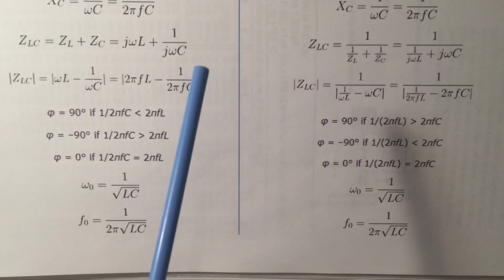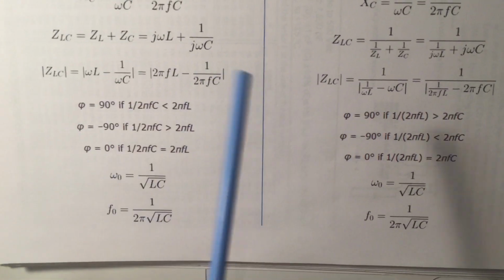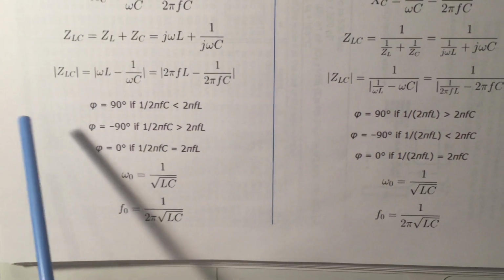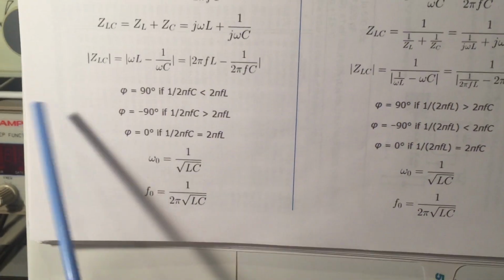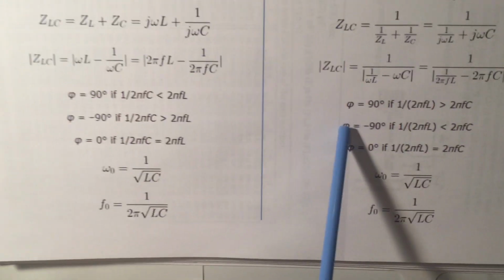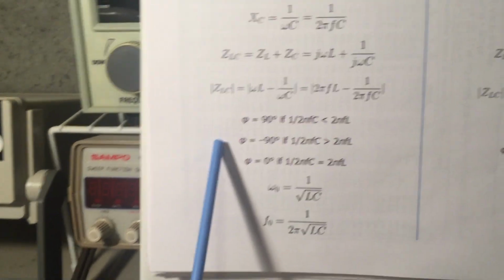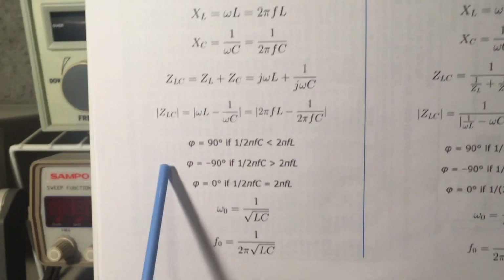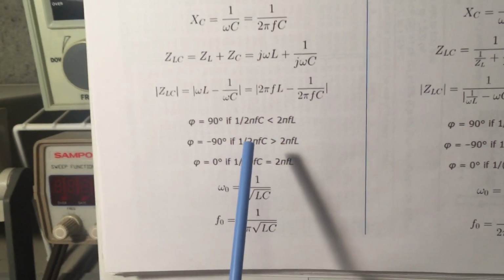So we have capacitive reactance measured in ohms. We have inductive reactance measured in ohms. Okay, the reactance or impedance is created by the phase shift. And as I said, in an inductor, the voltage leads the current, ELI, and in a capacitor, the voltage lags the current. So you have ICE. Just remember the word ICE, and you see the voltage lags the current.